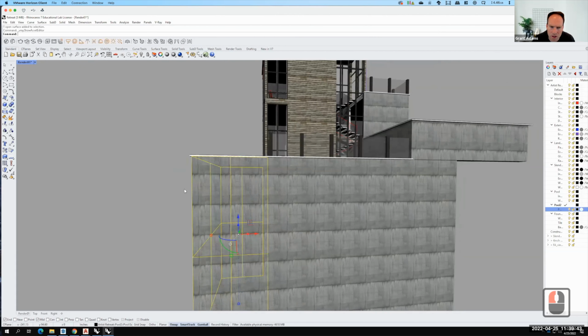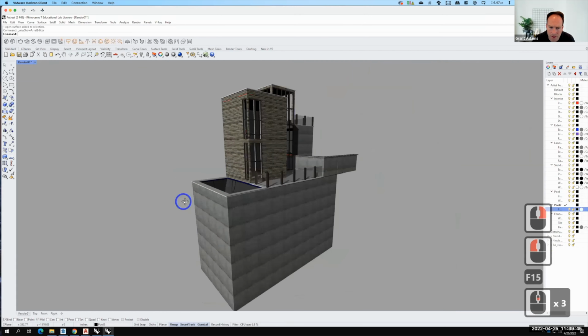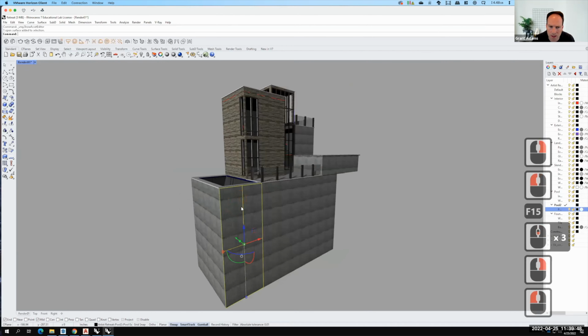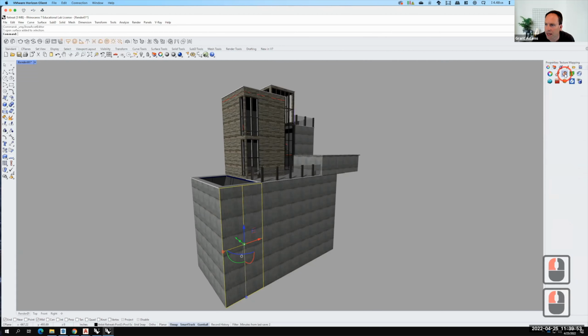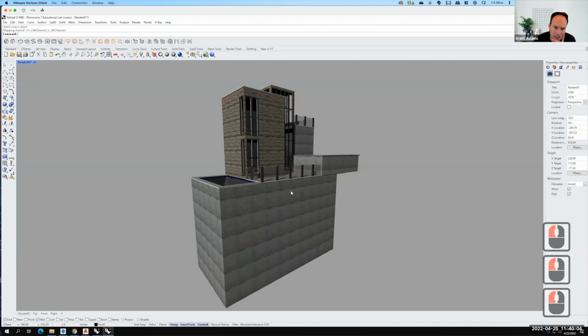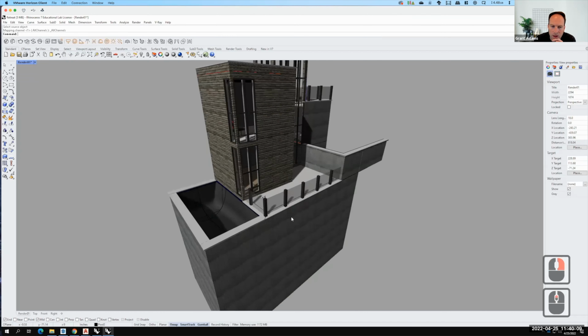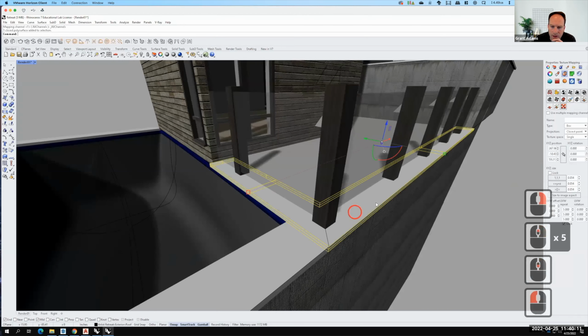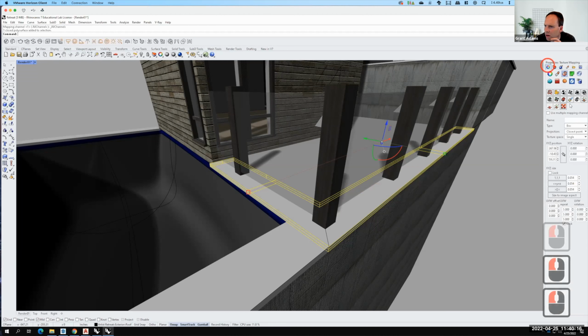It looks like I already texture mapped them. If I hadn't, I would want to take this, go over to my settings, go to my texture mapping. Let's pretend it wasn't done. So I just deleted the mapping. There's the original. And I would match the mapping to my existing wall so that the texture appears seamless as it goes forward. That's important. Then I could come down here and look at what this material was. And I actually don't know what it was set at.